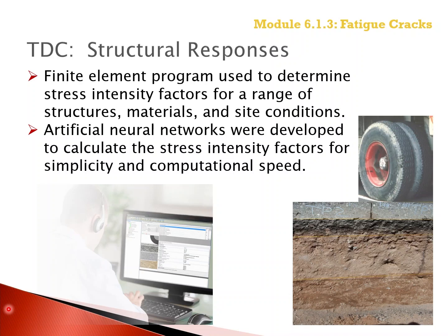The results from these computations were used to develop artificial neural networks to calculate the stress intensity factors used within the PMED design software for simplicity and computational speed, just like the artificial neural networks developed for rigid pavements.